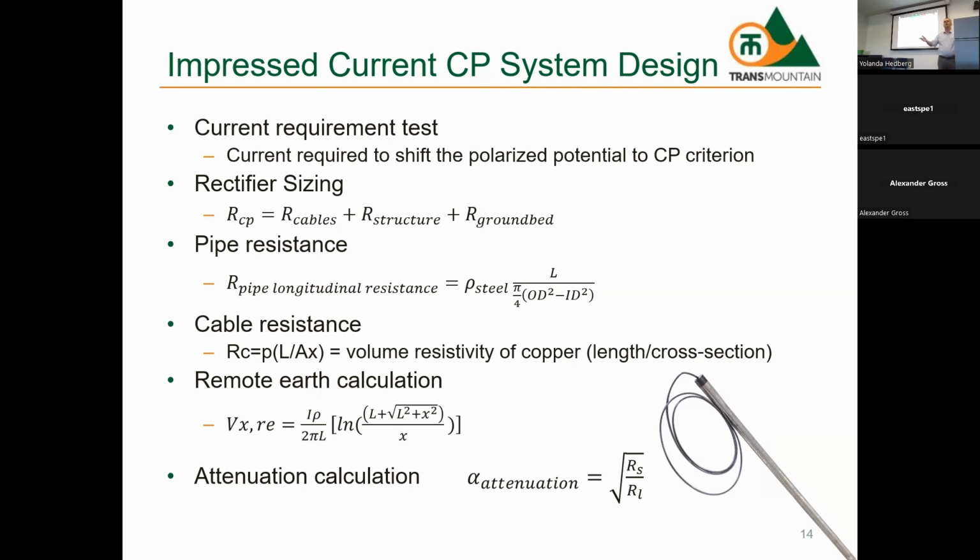So let's say I want to protect 10 kilometers away. You plug this into the two calculations based on your output, soil characteristics, and the pipe characteristics, to figure out, okay, I have 1 volt of driving voltage right here. How much driving voltage do I have 10 kilometers away? Is that enough to protect 10 kilometers away, or do I need more output? So as you get further and further away, you lose power. All right, any questions on impressed current systems?